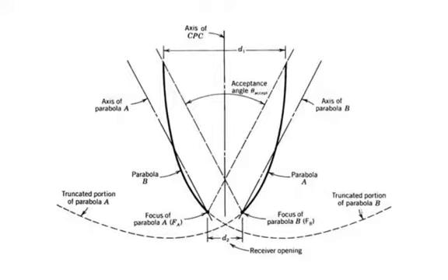Now, by the way, when you talk about accepting a small range or large range, that is very critical to designing a tracking system. If you need to only accept a very small range of angles, that means you need to track the sun very, very precisely. So it's an important engineering condition that we should keep in mind.